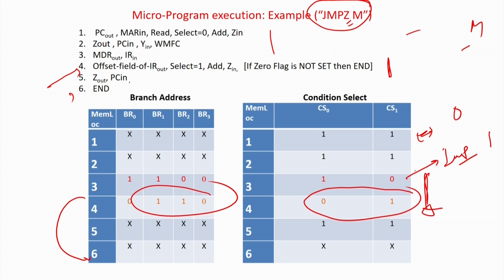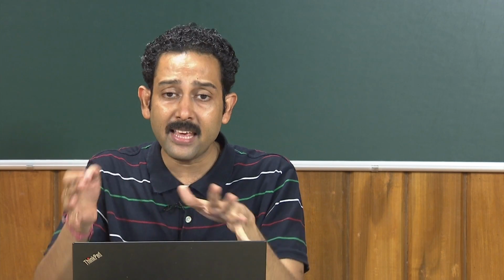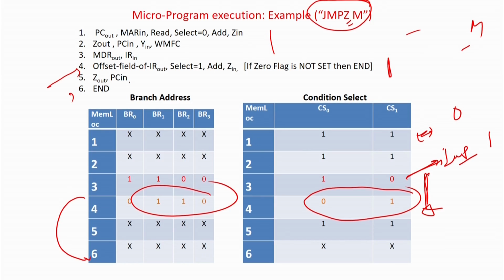The earlier instruction was the implicit jump because of the common microprograms corresponding to different macro instructions. That was happening because of optimization, but in this case this is explicitly required. The fourth jump is mandatory. Without this your program will not run correctly, but the jump at the third location corresponds to optimization.